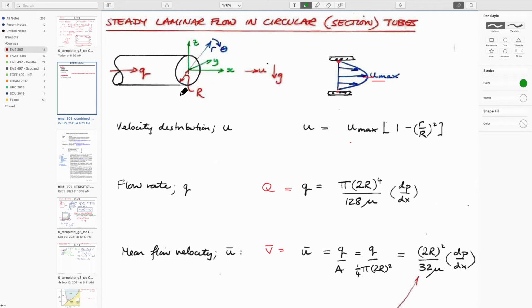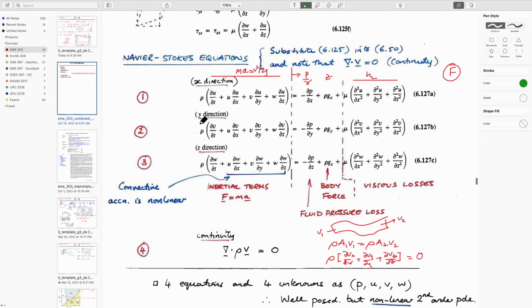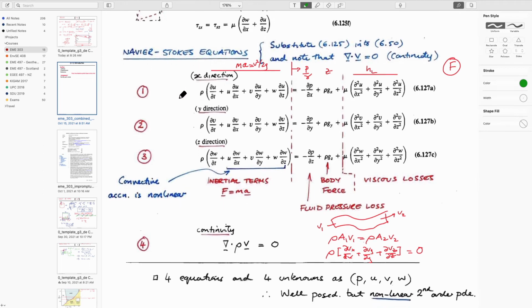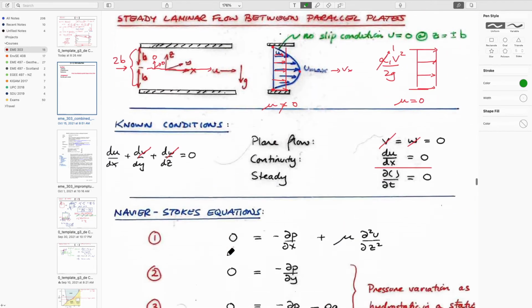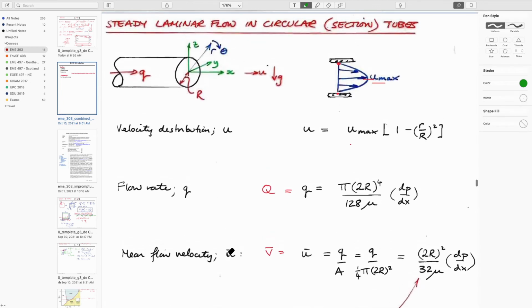We can choose the geometry for that as kind of a differential geometry. And if we use those kind of complicated expressions that we get, which we didn't spend much time talking about, but they were the so-called Navier-Stokes equations: 3 equations for conservation of momentum in each of the 3 directions along with viscous effects, and 1 equation for conservation of mass. Variables of velocities in 3 directions in an element and a pressure, so 4 terms and 4 equations.